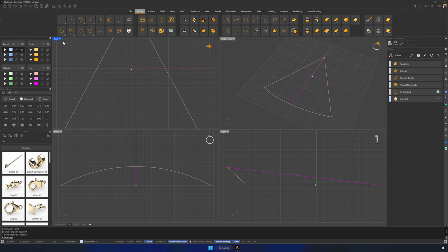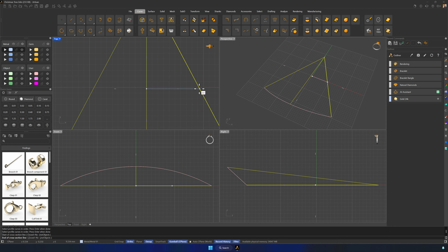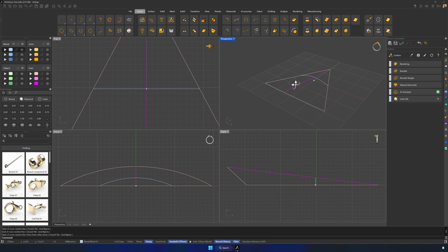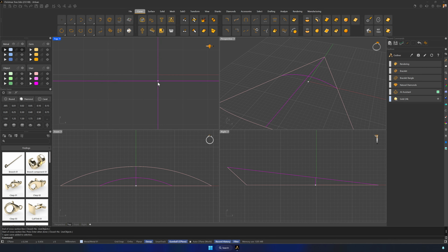Next, we'll create an arc using cross-section. Activate the command and select the left, center, and right curves. Click on the reference point, then hold Shift to draw a straight segment to one end. Change this arc to its own layer as well. Now we can delete the reference point.